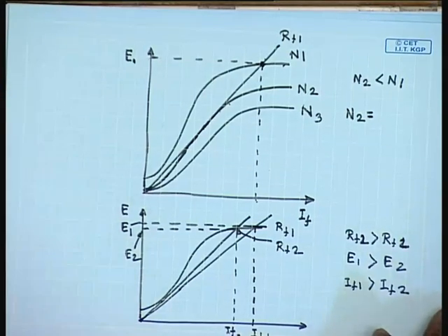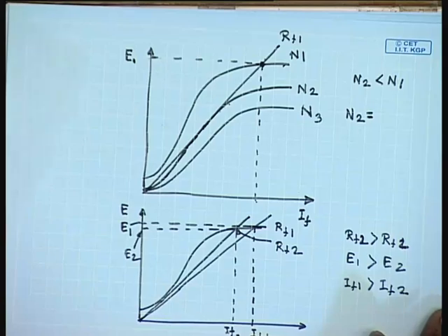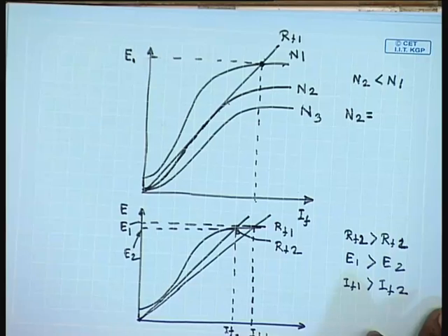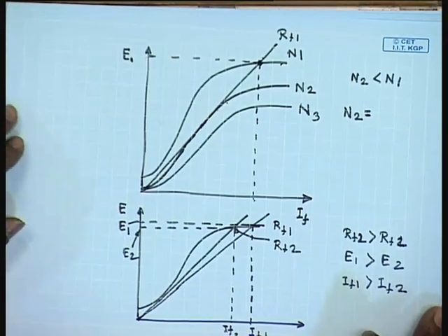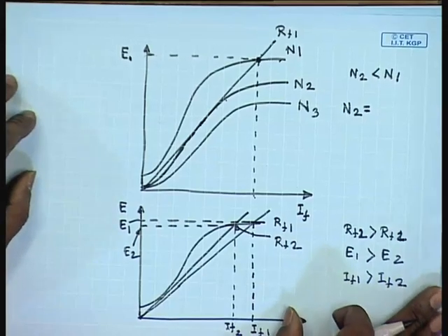Therefore, the no load terminal voltage of a shunt generator at any operating speed can be adjusted by adjusting the field circuit resistance. However, as we have seen for the separately excited DC generator, it is more important to find out the output characteristics, that is the external characteristics of a shunt generator.